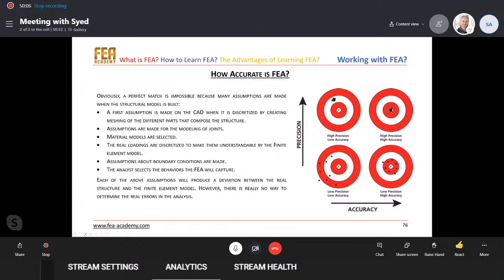For steel structures, this error is very small, since there is less than 1% variation in the modulus of elasticity of steel. However, when analyzing soil, for example, the error in material response could easily be 20%. It's an example. So the largest error in most FEAs is the result of bad boundary conditions. Incorrectly supporting your model can result in large errors that are transparent to the user.